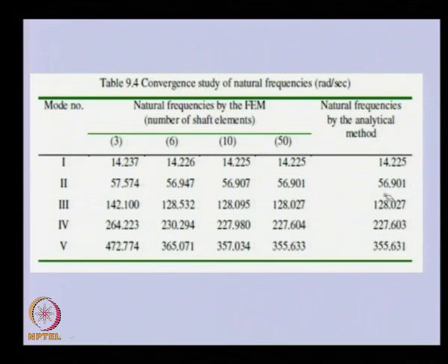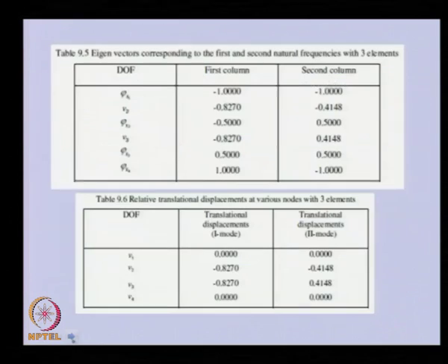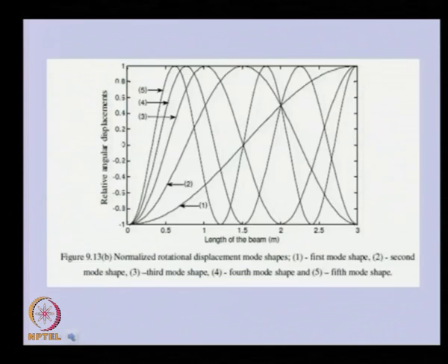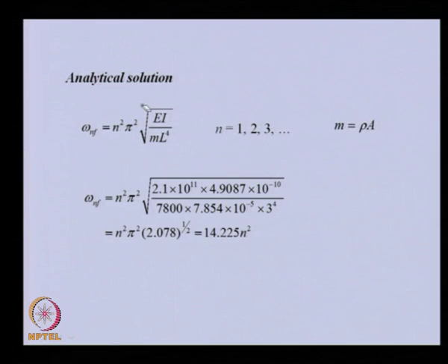And for calculation of this, this was the analytical expression for the natural frequency, where n is 1, 2, 3, 4, and we can substitute and get the natural frequencies. So, basically natural frequency is given by this. For the simply supported beam case, we need to put 1, 2, 3, 4 one by one here to get the closed form or analytical solution of this particular problem.